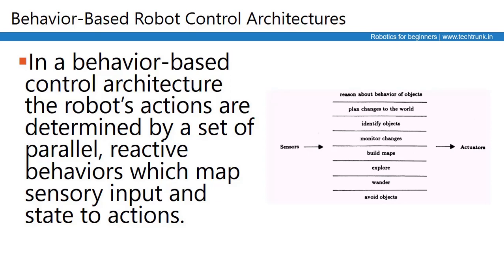So in a behavior-based architecture, the sensors feed the data which helps the robot perceive the environment, and rather than building the complete state of the robot in a very optimal way, for example, rather than making the complete vision system optimal, rather than making the complete reasoning system optimal, rather than making the acting or actuator system optimal, layer by layer execution is done.